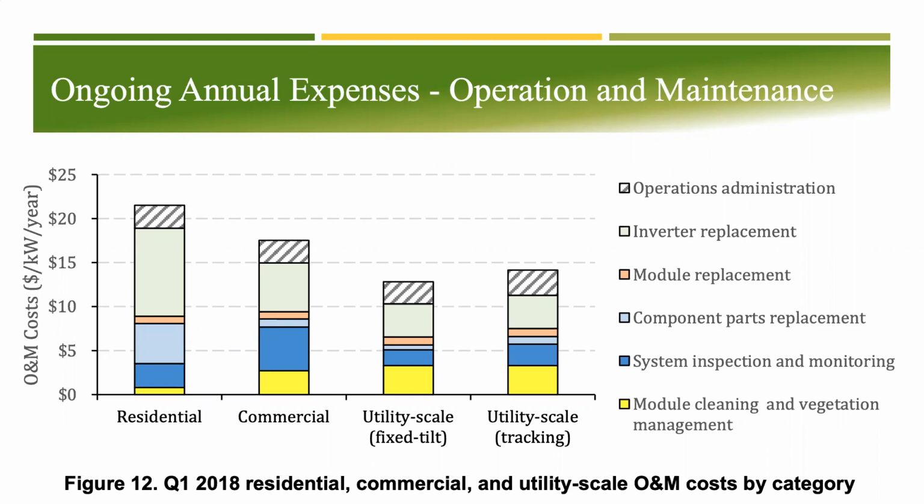So I compared two different projects. At the time, they were recommending $26 per kW for O&M. On a 30 kilowatt rooftop system that they were looking at, that would have added $780 a year to their cash flow table. And over the 25 years of the project, that would be $19,500.